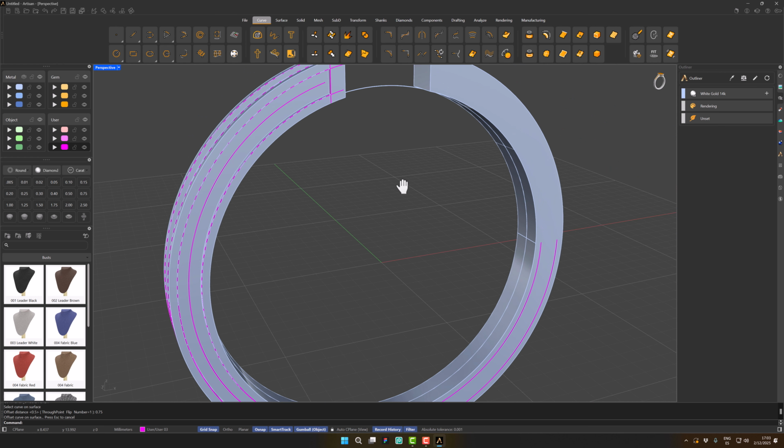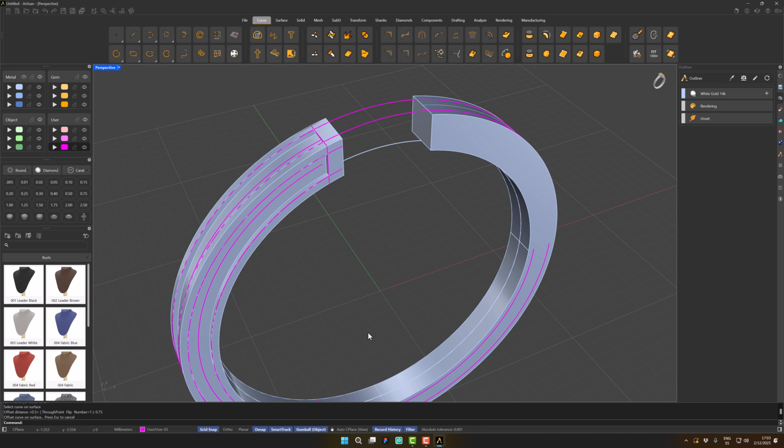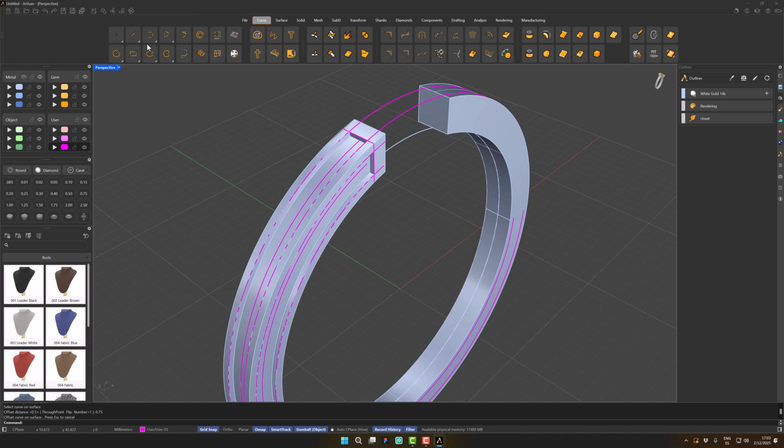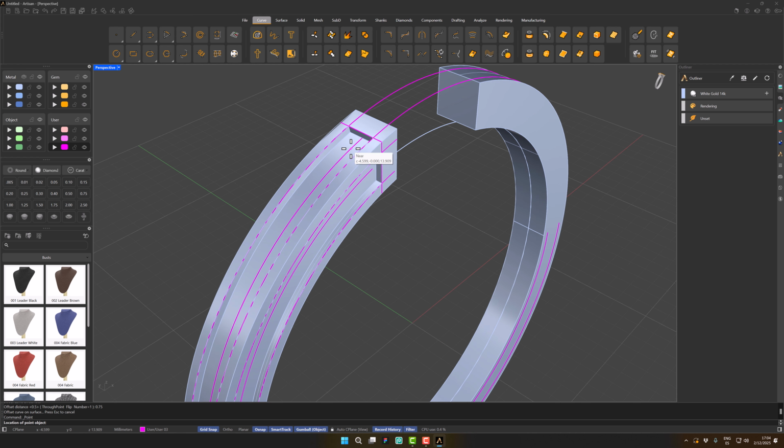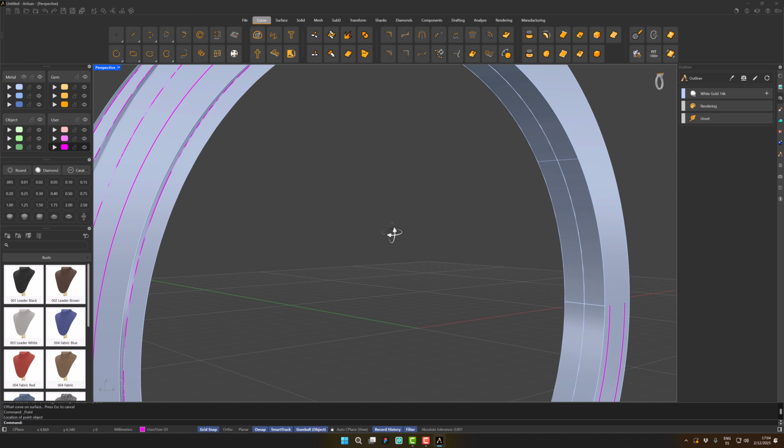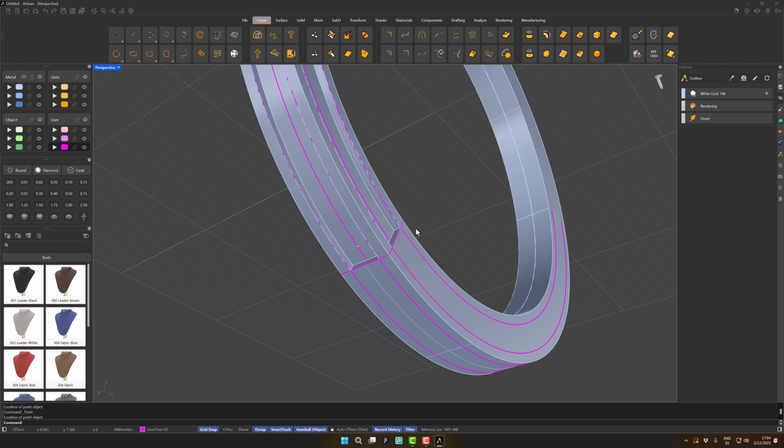Adjust the curves to prevent the gemstones from intersecting with the solid. We'll trim the curves to leave a margin at the edges. We'll use the Point command to select a point at each end of the created curves. We'll do this for all 4 ends.